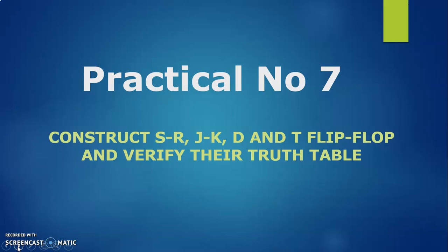In this topic, we have latches and flip-flops. A latch is a type of temporary storage device which has two stable states. It is different from a flip-flop. Both of them are basically bistable devices having two stable states, which means one is 0 and one is 1.